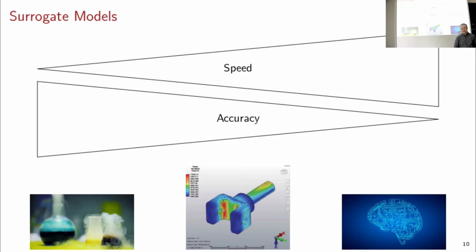I guess that means you need a lot of expert knowledge to design the space then. Well, to some extent, yes, but in our case, this is essentially determined by the safe operating limits of the machinery. We have the reaction chamber, and that is safe up to 100 psi or something like that, and of course, we're not going to set it higher than that. What does happen in some cases is that we are literally just burning through the material. And that's fine. This is set up in a way that it will not set the rest of the building on fire. That is obviously a bad result, and we can take that into account in the optimization, but it doesn't blow anything up or set anything on fire.